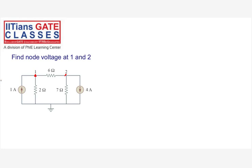So at node 1, tell me the currents in terms of voltages. I'll take all the leaving currents here. Leaving current here will be -1. The leaving current here will be V1 by 2. Leaving current here will be (V1 minus V2) by 6 is equal to 0.